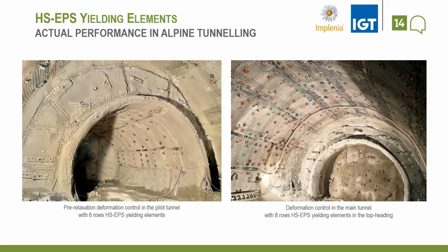And with this combined system, using a pilot tunnel and applying the, let's say, optimized stiffness or stress-strain response of the yielding elements, a dense bolting pattern, and a really flexible construction process, it is even possible to tunnel as economic as possible and as safe as possible in such really difficult ground conditions.